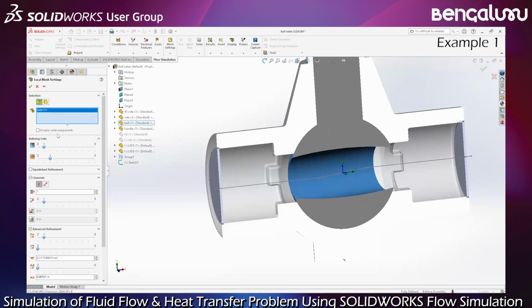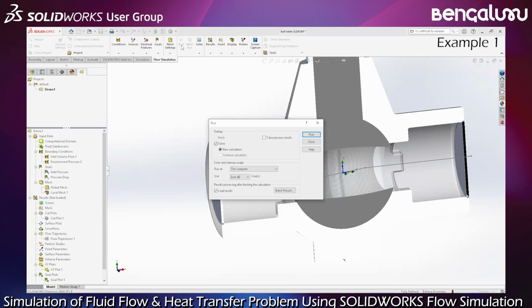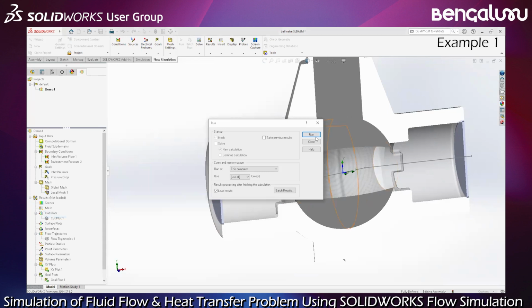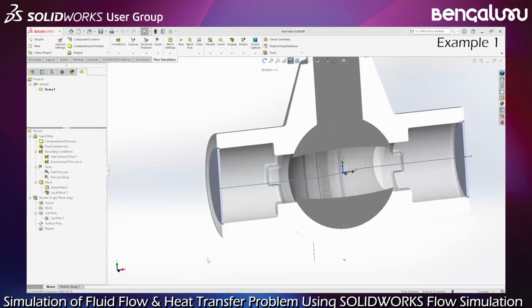So let's just use what we did here, okay? I'm just going to run, but just the mesh. I just want to create the mesh and check. I can do it there, or I can go here to the mesh and say create mesh. Okay, run. So it opened the same. Done. Of course, now I have overwritten the previous calculation. No results except the mesh.